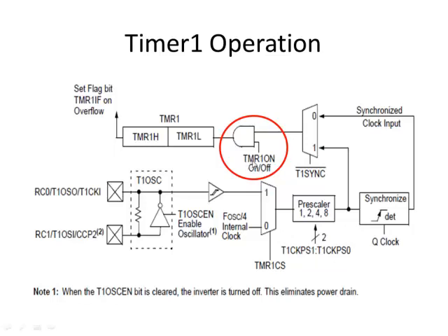Okay, there's a bit in the control register called the timer 1 on bit. Okay, and that just turns the timer on or off. It doesn't actually turn power on or off. What it does is it allows clock pulses to come through. Okay, remember how an AND gate operates. You can use this sort of to allow this signal to go through. What I'm doing here is, with this bit, if you've got a 0 on one pin of an AND gate, what is the output? The output will always be 0 regardless of what's going on here. So if this is a 0, basically it's turning the timer off. It's saying, I don't care if clock pulses are coming in, they're not getting out, and they're not reaching the timer. When this bit is a 1, every time you get a pulse here, that pulse will come over here.